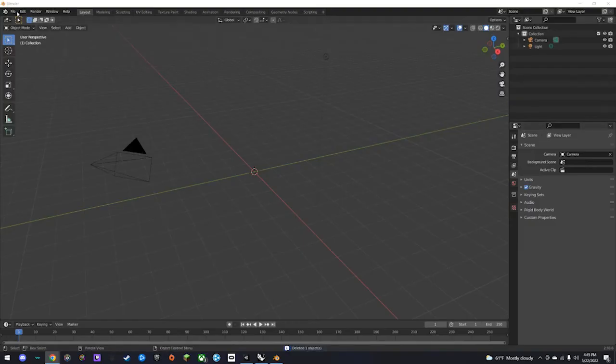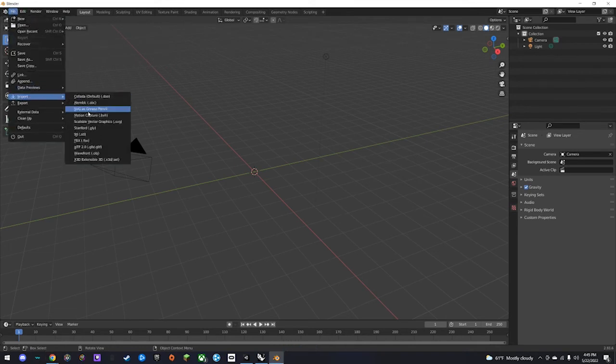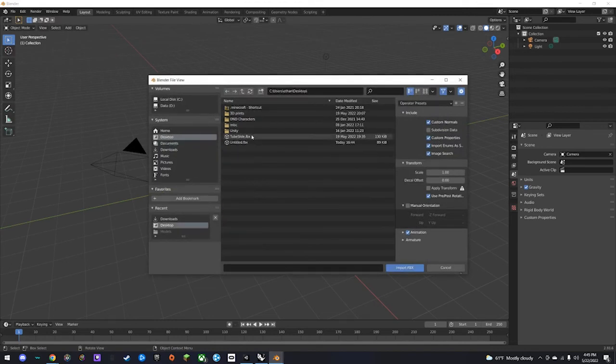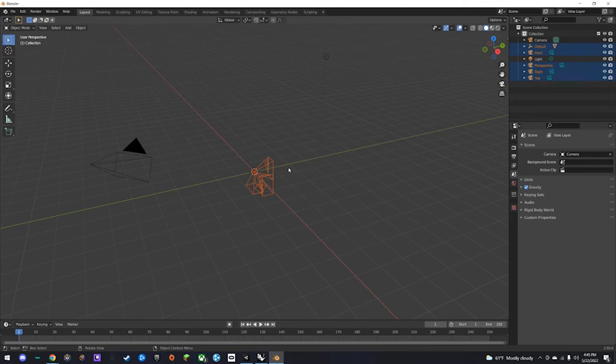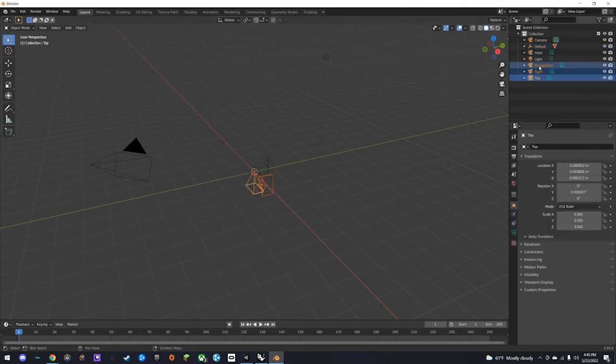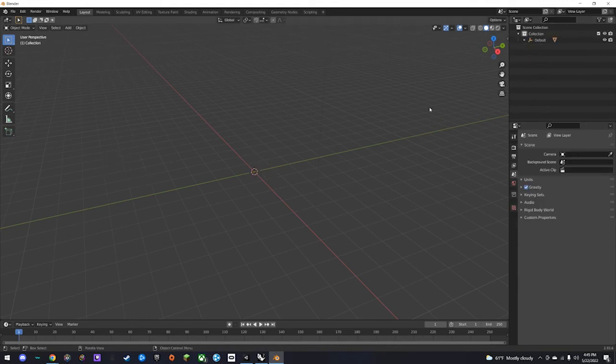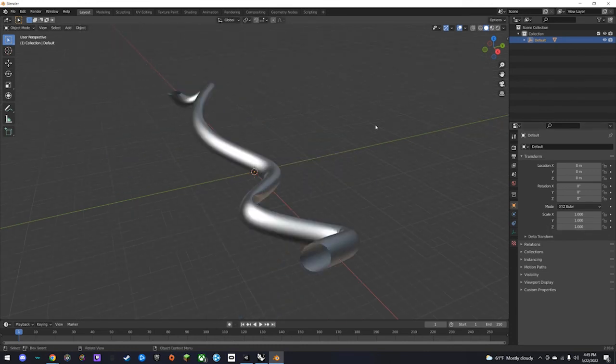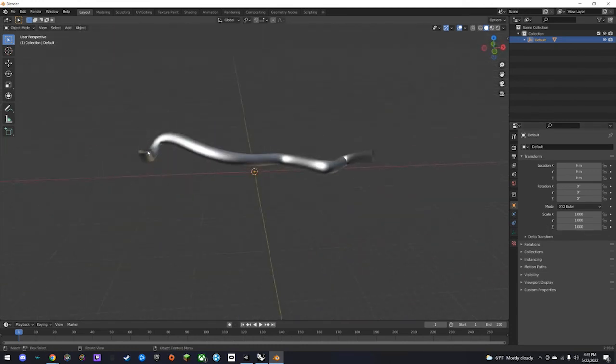The next step is to open Blender, go into File, Import, and click on FBX. Then go over to your desktop and load in the actual file. It's going to be really small, and you're going to delete all the perspectives because they just mess with it and aren't helpful. Then click on it. The scale starts at 0.001. You want to change that to 1, or whatever size works for you. As you can see, it is now here.